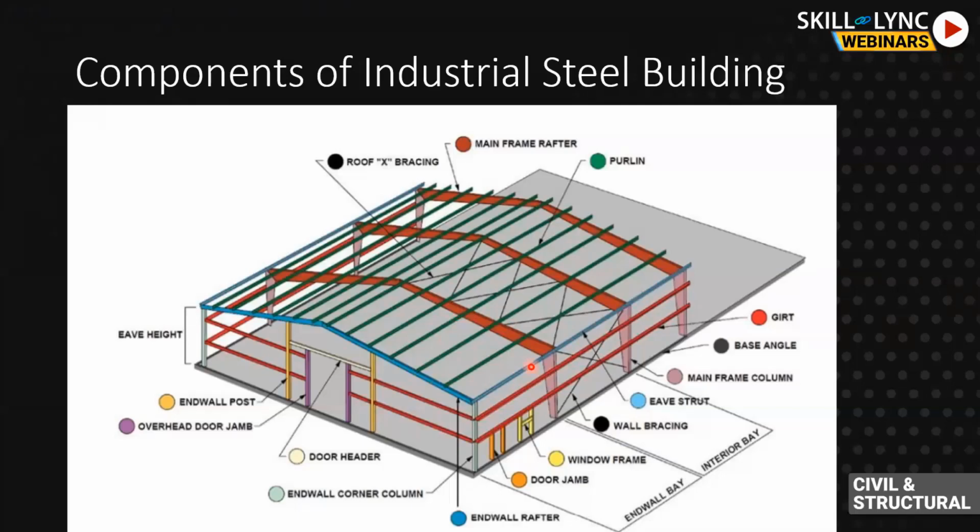But in case of a steel building, you achieve rigidity along the width of the frame, and a lateral stability system is required along the length. So bracings are provided along the length. So the bracings can be of different types. Either it can be X bracings or A bracings, inverted A or K bracings. There are lots of types of lateral stability system that we come across. Here in this figure, we have X bracings. So X bracings can be steel rod or anything, any member which can take tension or sometimes compression.